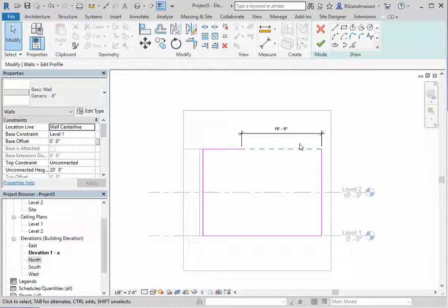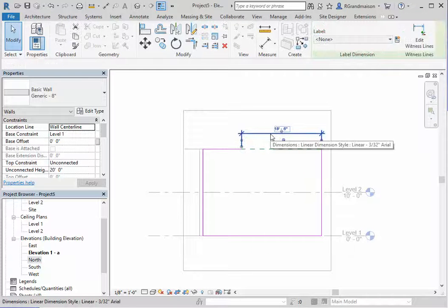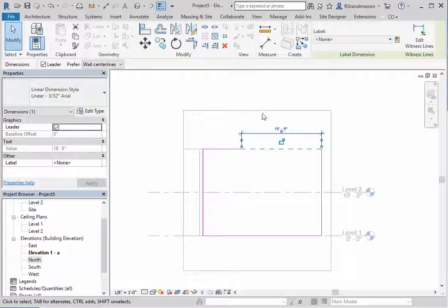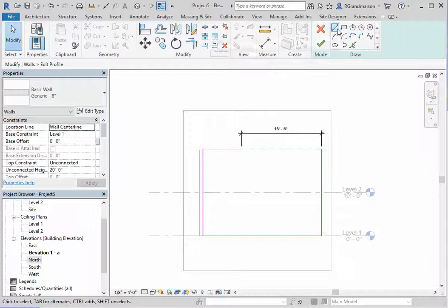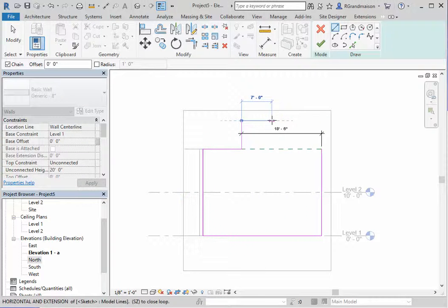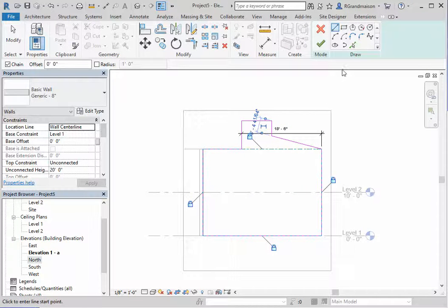So now I've created this gap here that I need to fix, and to fix that I'm just going to go ahead and sketch. So I'm going to pick maybe the line tool here, and I'll sketch up like this and across like this, and maybe at an angle like this. And you can see I'm using my O-snaps as I do this.